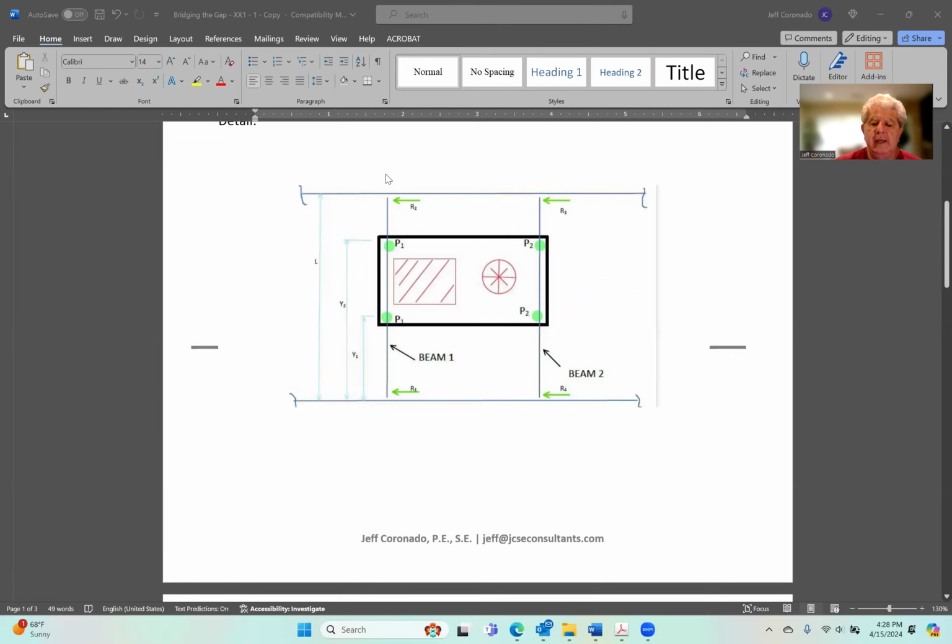So what that means is if the load of the unit was symmetrical, then these loads that represent the weight of the unit, P1, P1, P2, P2, if we were to get the four corner weights and add them up, we will get the totality of the weight of the air handler, of the mechanical equipment. However, since it's not symmetrical, they won't all be equal.